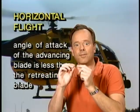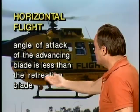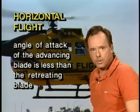Well, the advancing blade is actually going faster through the air, through the relative wind, than the retreating blade, so therefore it has to have a smaller angle of attack. So the angle of attack of the advancing blade is less than the angle of attack of the retreating blade.